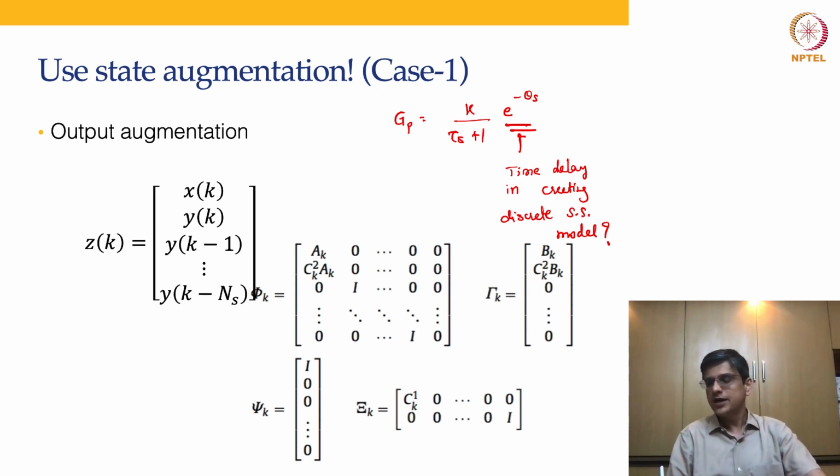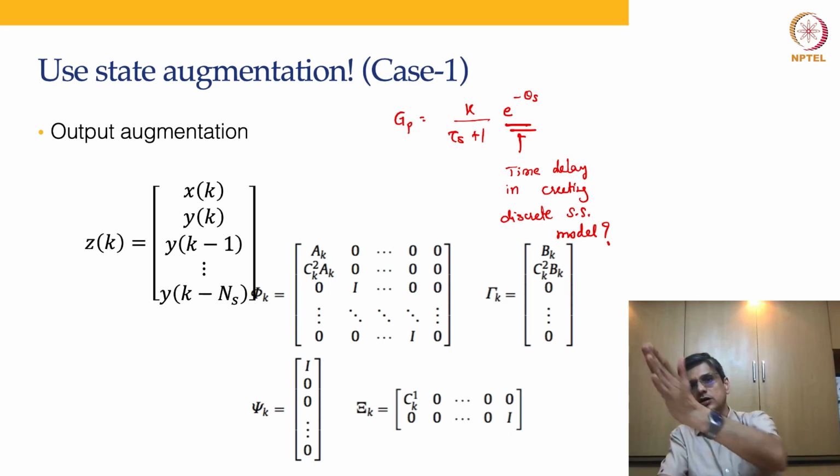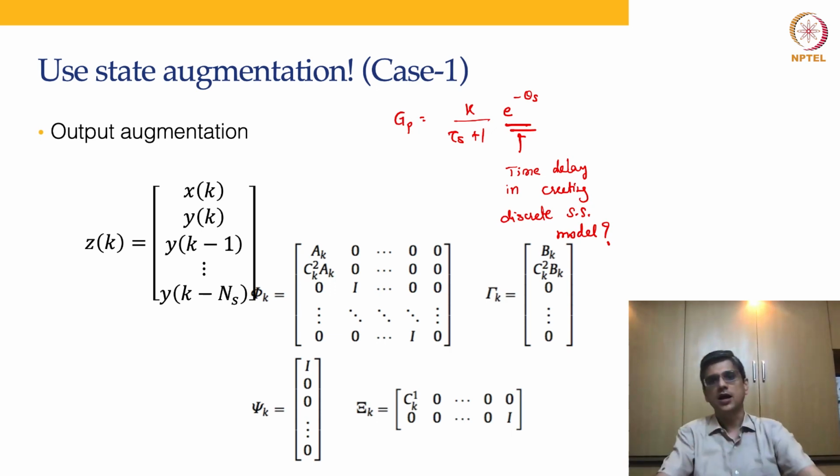You know how to do that, and if you remember, we had stacked up past delay models, u(k-1), u(k-2). Those were input delays. Here these are output delays, equivalent, not the same. An input delay is like you have a pipe, the input comes in at this end of the pipe and it takes 25 seconds for that input to come into your reactor. So you have a 25-second time delay, which would be 25 divided by 60 as your theta if your measurement time is 1 time unit.